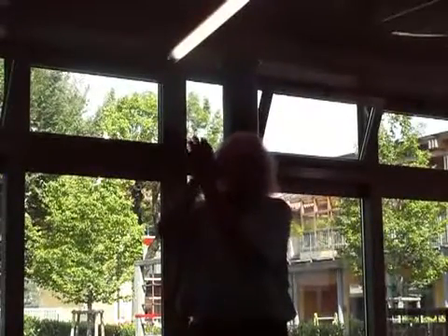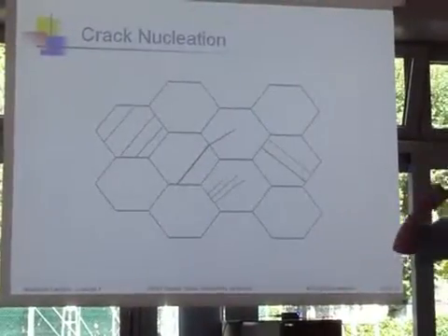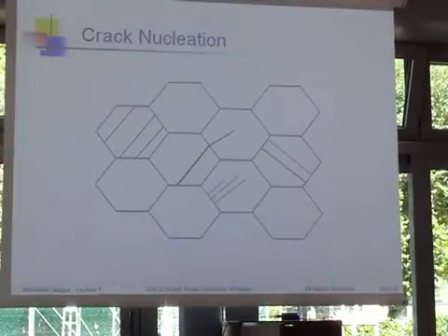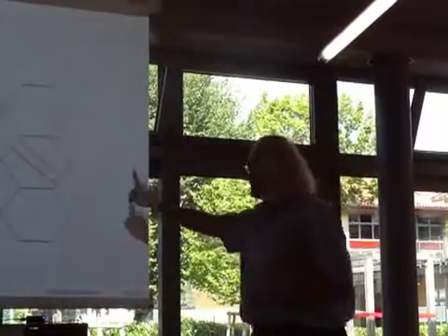And this is why I spent a minute talking about pushing the rug across the floor. In that during solidification, every one of these crystals will solidify with some random orientation of planes. And if I think about the orientation and I wanted to form something easily in shear, then there's a preferred direction for which it's easy to shear and another direction for which it is not. And so if I looked at these grains, maybe this crystal is oriented such that the preferred shear direction is like this. What's the shear stress on this plane when I load this in tension?